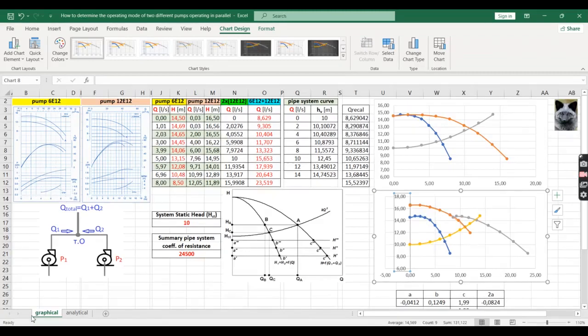As can be seen, the determination of the pump system operating parameters may be performed in a similar way as the previous case discussed in this video. However, determining the operating parameters of each pump requires to indicate the specific features of the system, as well as to take into account the equations describing their head curves.